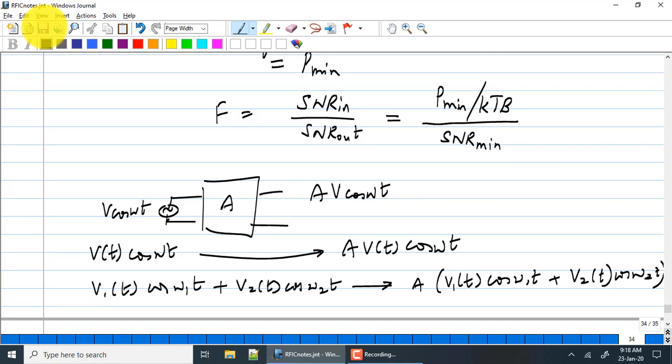You take the signal representation that we have normally studied, V cos omega t, a sinusoid. Now you get the components of this signal varying over time. As you can see, normally you can think of the amplitude varying over time, which is what I have shown here. I could also have visualized the signal in a different way. I could have thought about the frequency of the signal itself varying over time. This would be FM, frequency modulated signal.